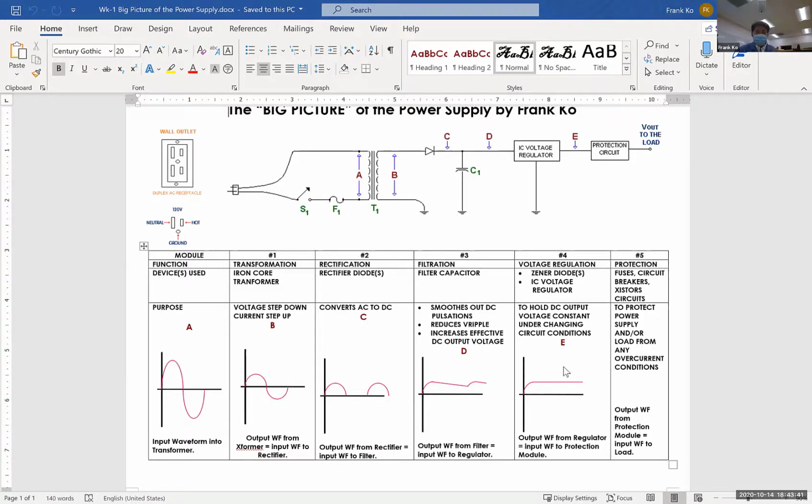You start off with 3 AA cell batteries, each one rated at 1.5 volts, giving you a total of how many volts? 3 AAA batteries in series gives you how many total volts? 4.5. And it will give you more than 4.5 with the new battery pack. You might have 4.6, 4.7, but over a period of time, it will drain, and then it'll become 4.5 and 4.4, 4.3. So you could not rely on the battery packs to give you a consistent 4.5 volts for